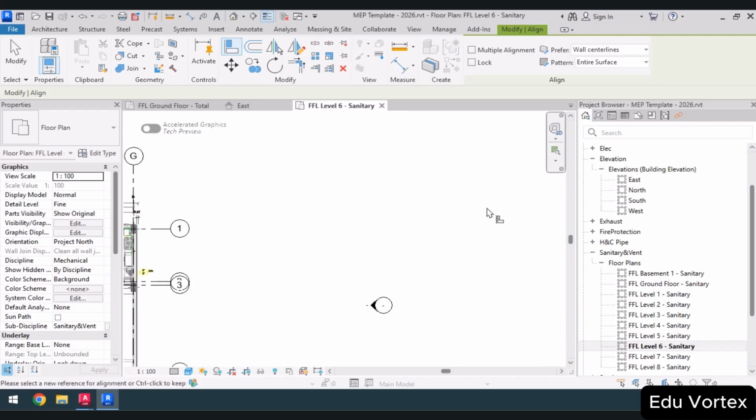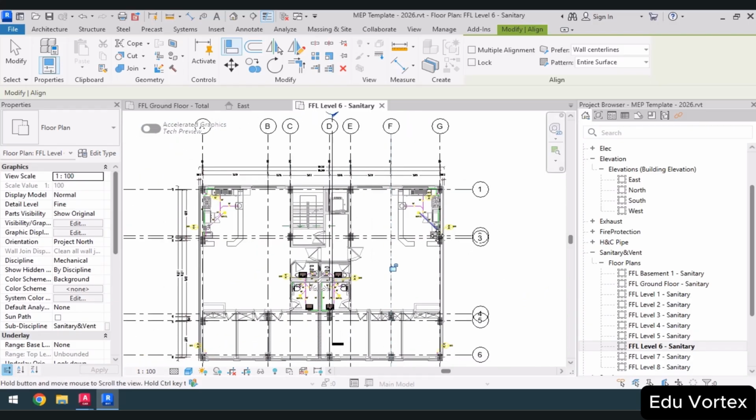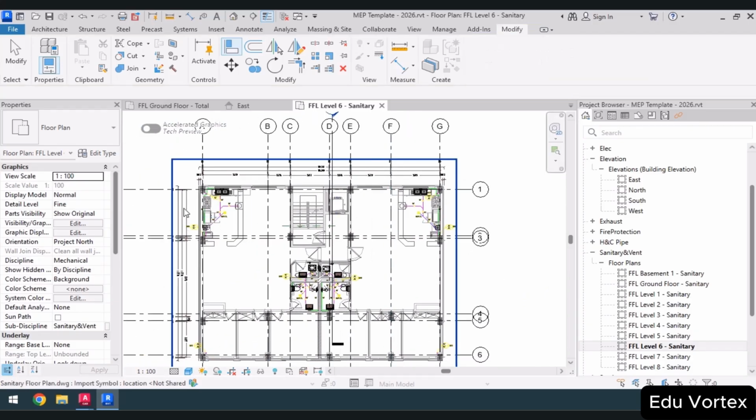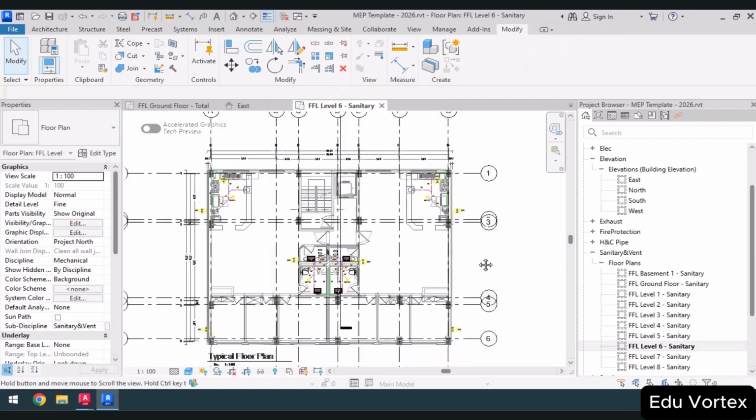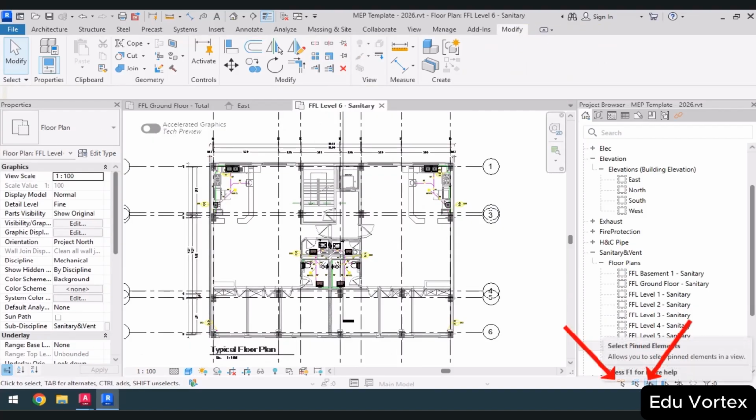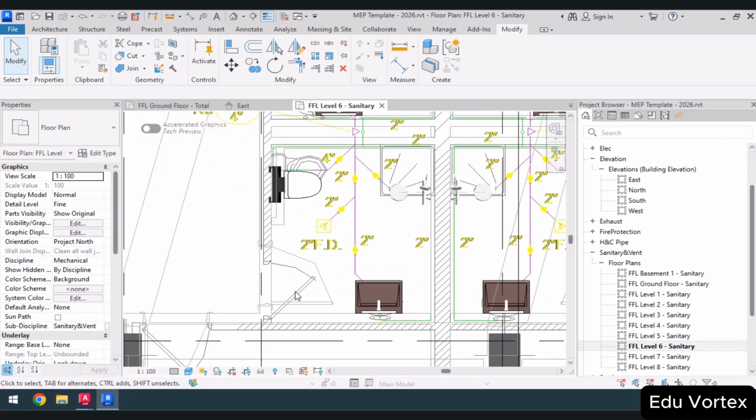So keep selecting and pinning the plan to ensure it doesn't move anymore. You can also click on select pin element and select link at the bottom so that the red cross appears, ensuring that the plan cannot be selected again to avoid any disturbance during modeling.